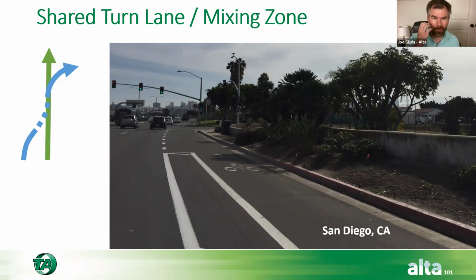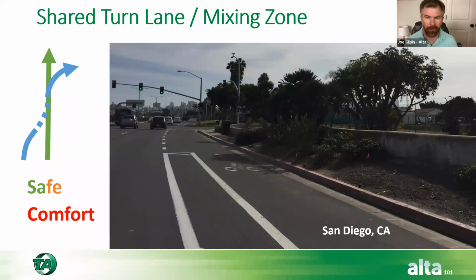And we're also keeping nice alignment on the far side. Bicyclists can clear the intersection and be directly in the bike lane again on the far side. So again, we want to keep this as short and compact as possible. You're not going to have huge right turn volumes in this case, but it is an option out there. And to me, this is a little bit safer than what we just saw, because it's going to have more certainty in terms of all of the vehicles using that space correctly. But again, the comfort is lacking because you're bringing cars into the bike lane and you're sort of terminating it. And this can be done with a traditional buffer, like we're talking about here. So the bike lane plus the width of the buffer can equal the width of a right turn lane.